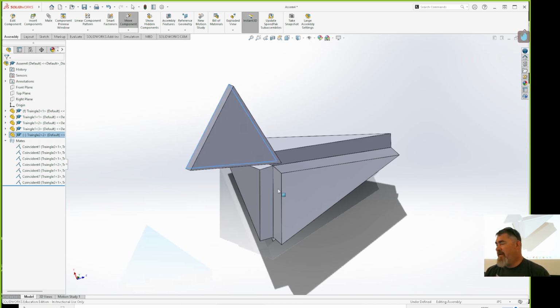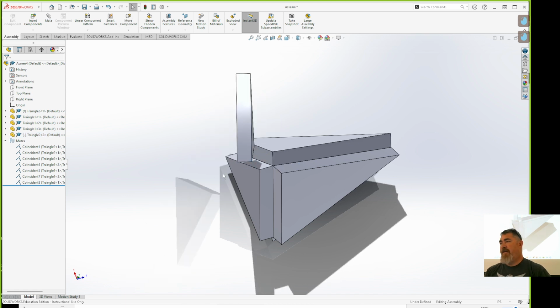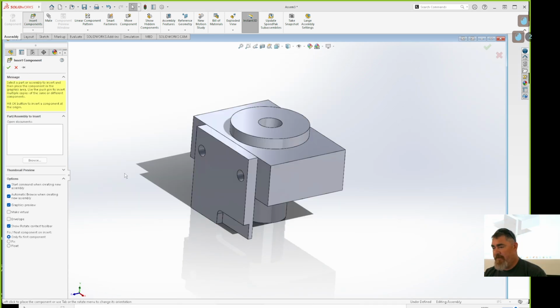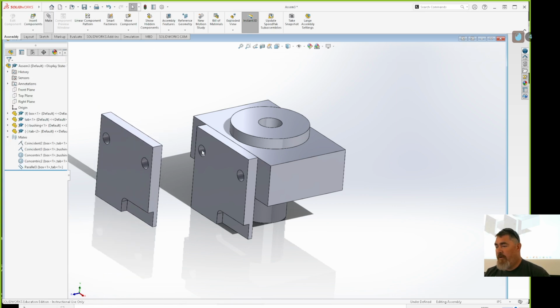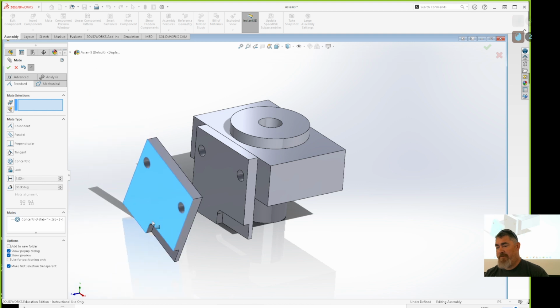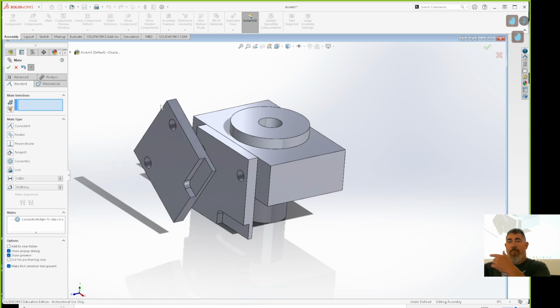So kind of like the pin and slot constraint or joint in Fusion, right? If I did just a linear constraint or an axis constraint, so let's say on this one, throw in another one of these tabs, and I did a joint between just these two, it can come and spin and slide. That's like the cylindrical joint in Fusion, right? So you can see how they kind of relate to each other just based on which ones you pick. It kind of has those same things.